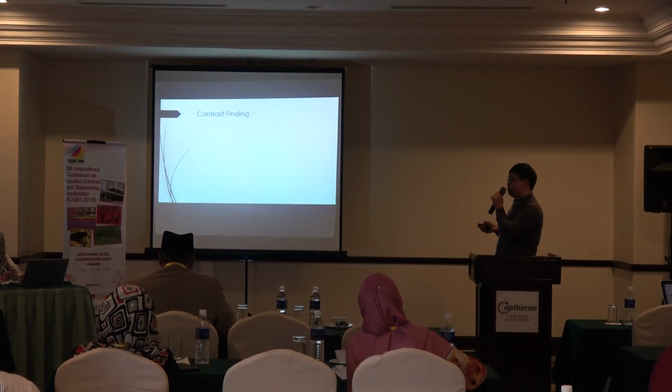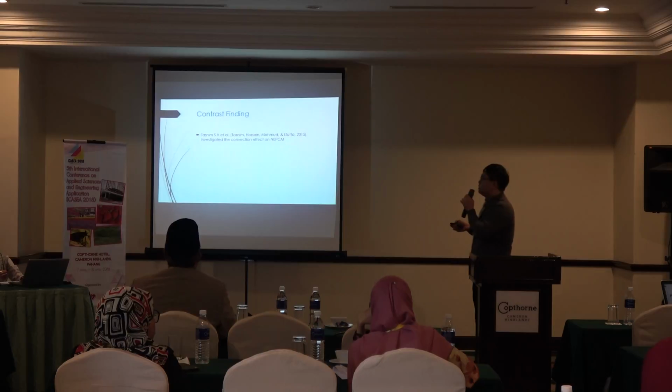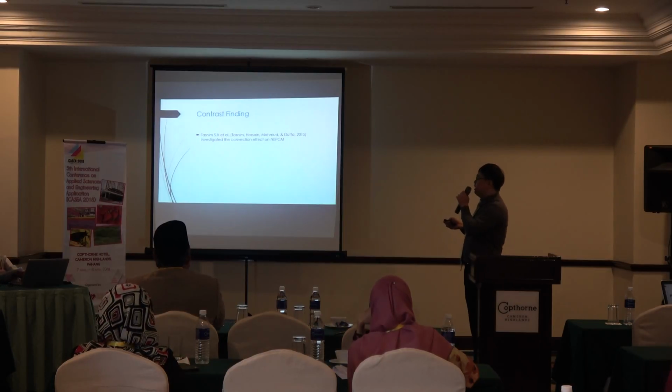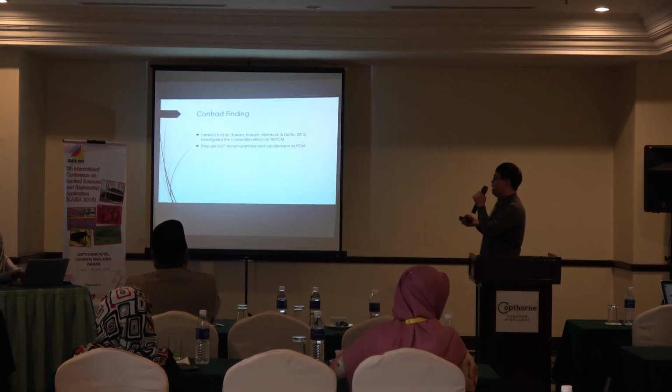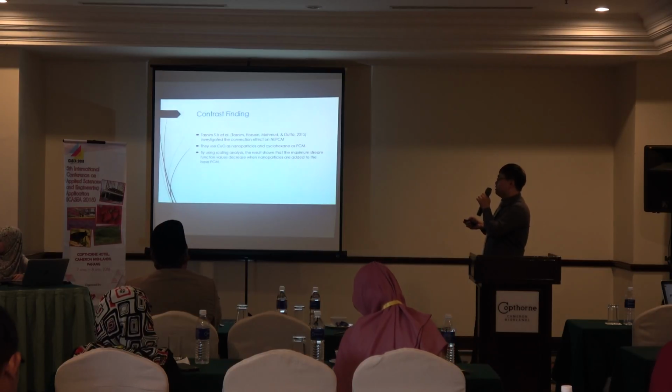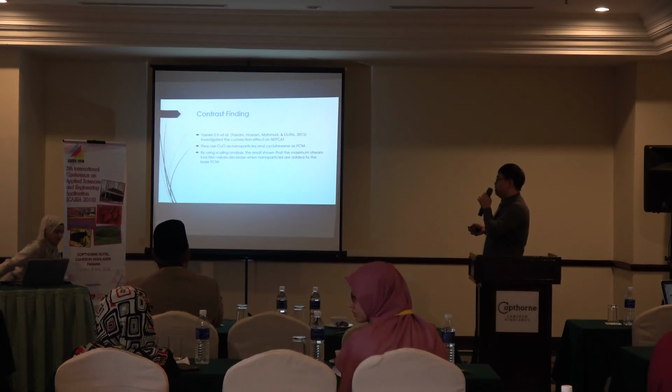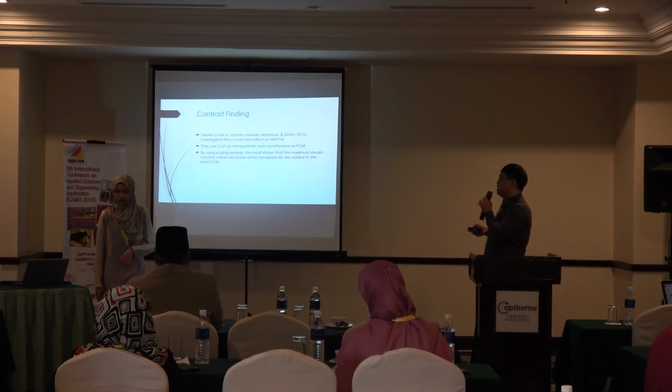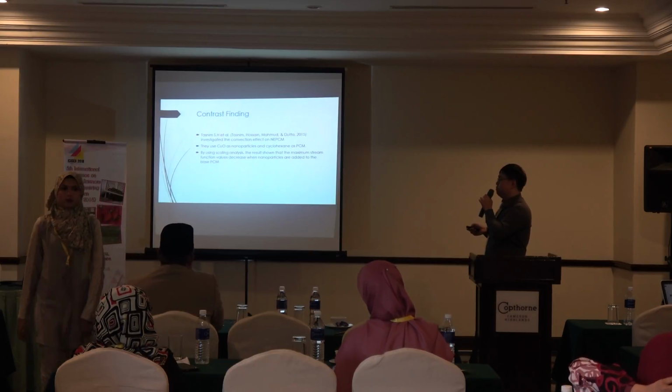However, there are also some findings that disagree with the enhancement of the PCM by adding nanoparticles. Haseeb and his group found that when using copper oxide as the nanoparticles and cyclohexane as the PCM, by using streamline analysis, the results show that the maximum stream function value decreases when the nanoparticles are added to the base PCM.